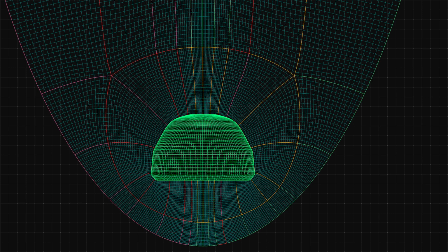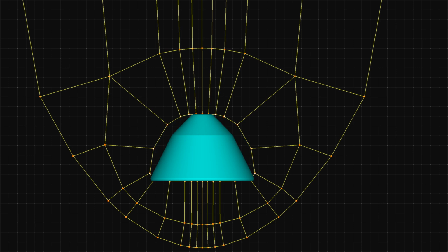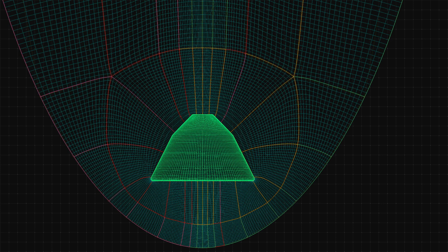Think of it this way. We already have a high-quality converged grid for our initial design. By replacing only the modified surface in the topology, we can rerun the grid smoother and focus its efforts solely on that updated surface. The grid for the rest of the domain will be a smooth, high-quality grid already, so time is saved. This approach offers a major time-saving advantage.